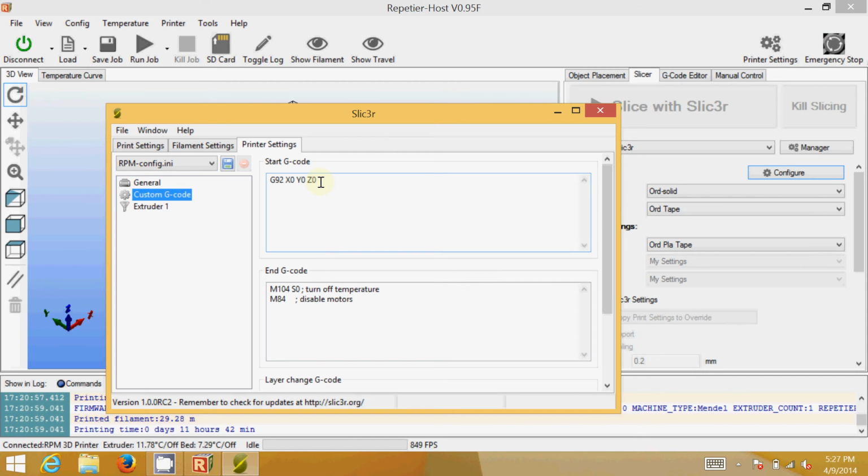So it's very important that before you start a print job, you go and manually home the print head. So you want to move it to that forward left position, so closest to you to the left, and get the print head right down on the print plate. You pretty much want to have the width of one piece of paper between the print head and the print bed. So you can just get it down close, then you start doing the negative 0.1 millimeter steps until you start feeling a little bit of tension on a piece of paper that's just sliding underneath it.